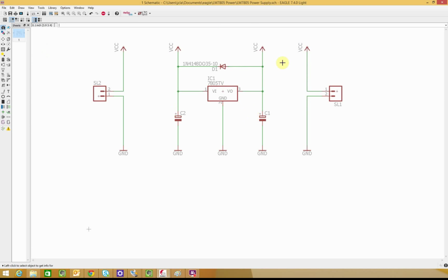This effectively means that all of these wires are connected together, meaning that we will short circuit this, or at least remove its functionality, since we will have the input here and the output connected directly over this. So this will not work. We need to separate this VCC grid from this VCC grid.